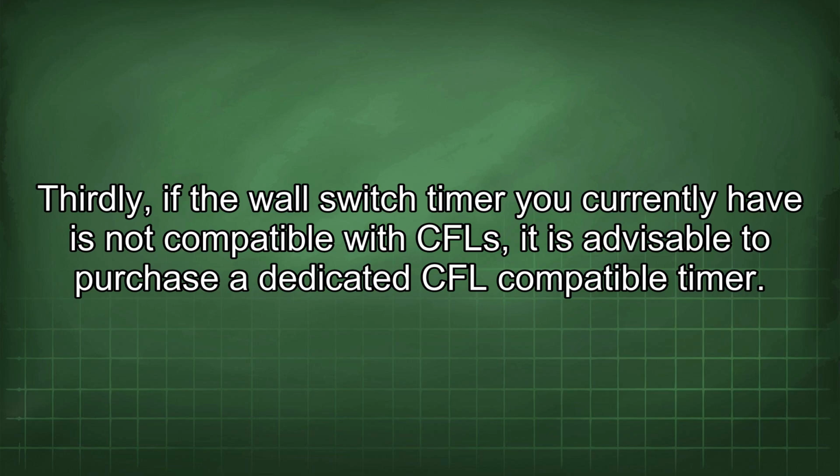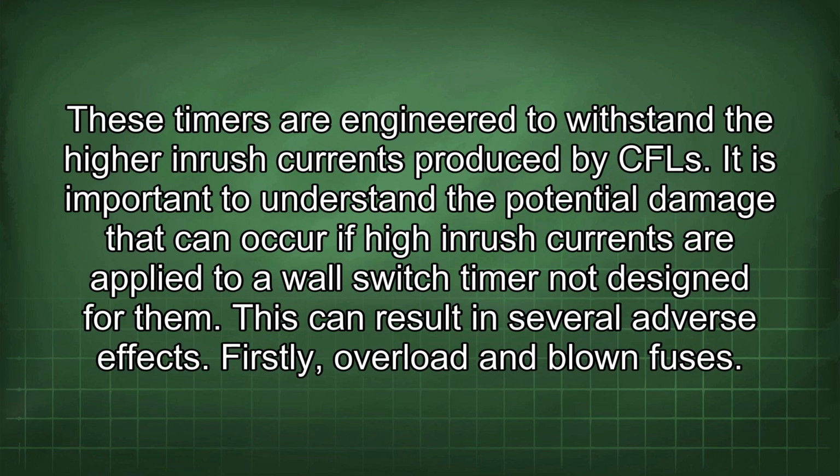Thirdly, if the wall switch timer you currently have is not compatible with CFLs, it is advisable to purchase a dedicated CFL-compatible timer. These timers are engineered to withstand the higher inrush currents produced by CFLs. It is important to understand the potential damage that can occur if high inrush currents are applied to a wall switch timer not designed for them. This can result in several adverse effects.